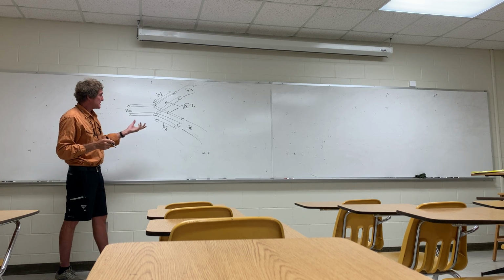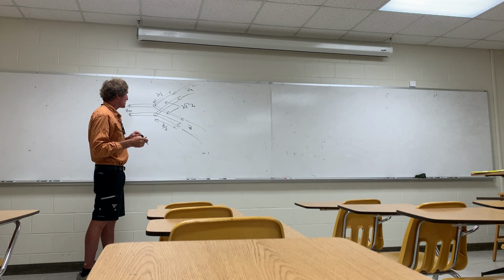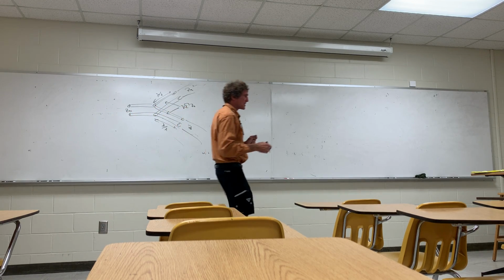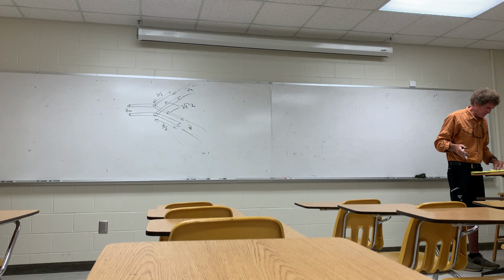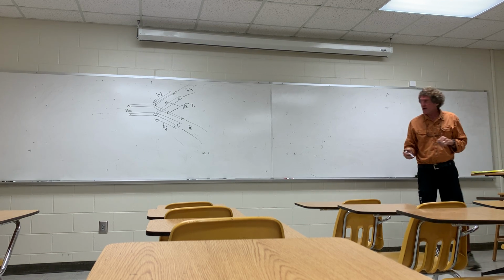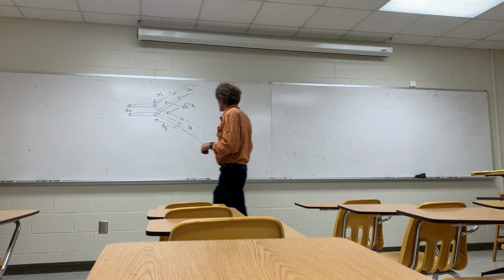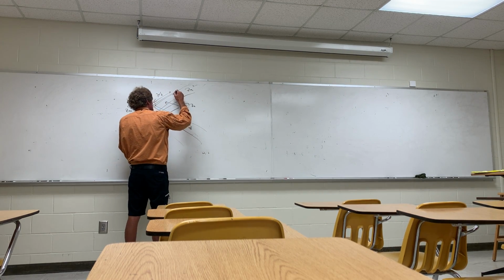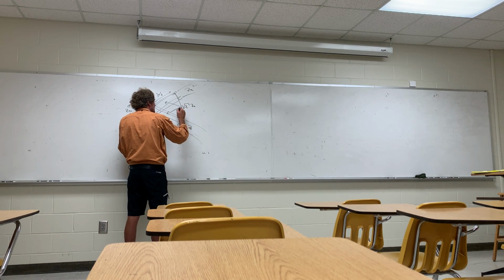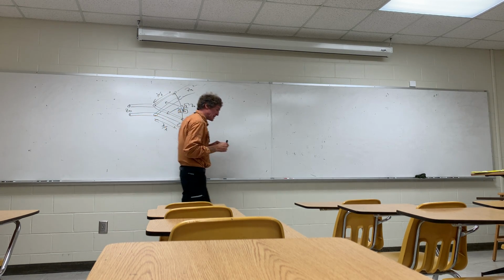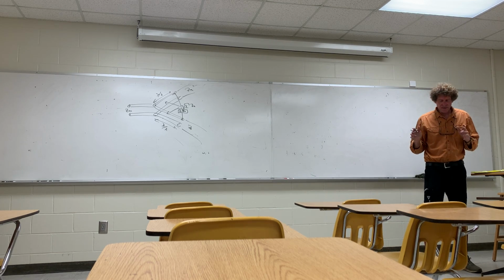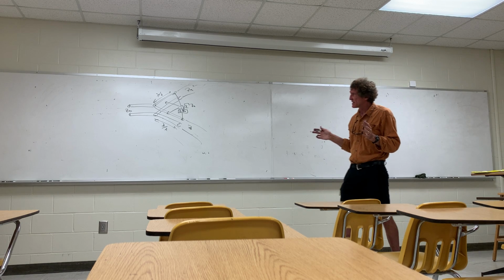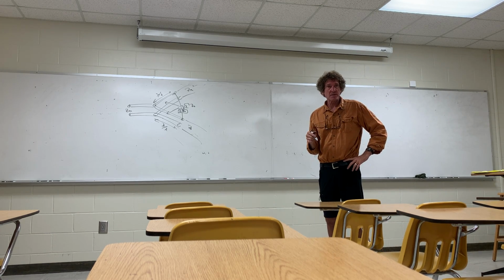So now the characteristic impedance of these 2 lines that are exactly a quarter wavelength long is square root of 2 times Z0. And I think he shows it better than I'm drawing it on top of page 571 if you look there. There's one other added feature between the tops of these 2 things. There's going to be a resistor. The value of that resistor is 2 times Z0. I believe it's twice Z0 in his book. That resistor ideally will not have any current flowing through it, but it's there for a reason. Can everybody follow me on this?